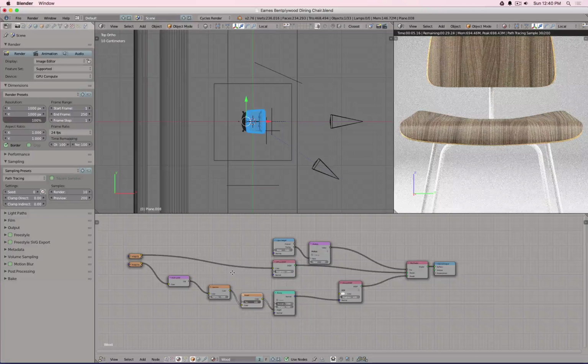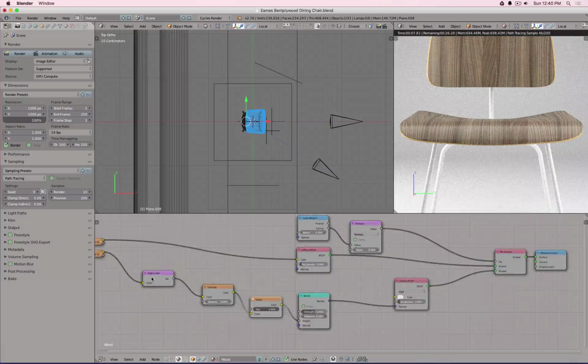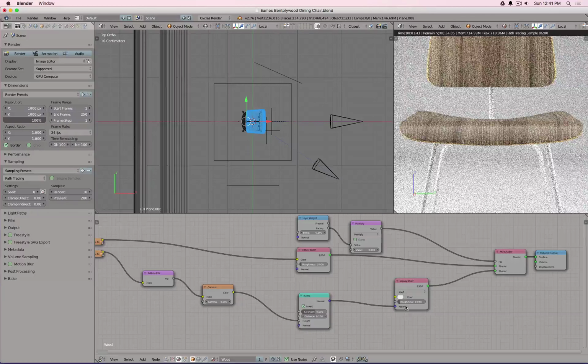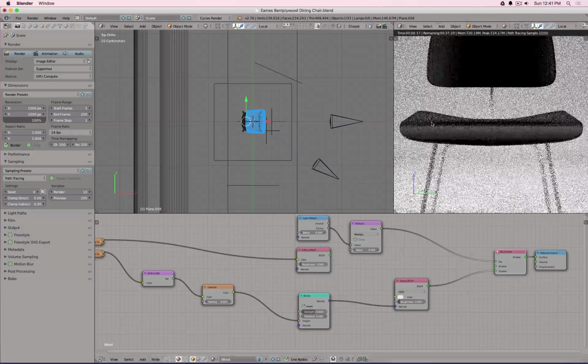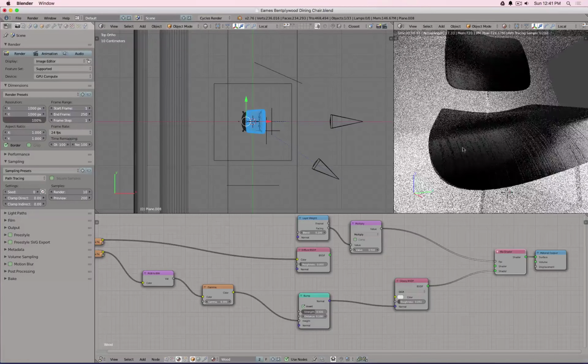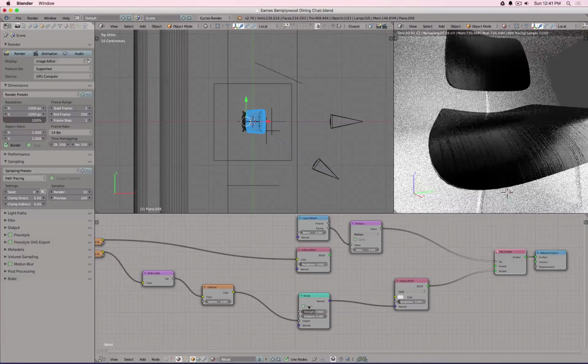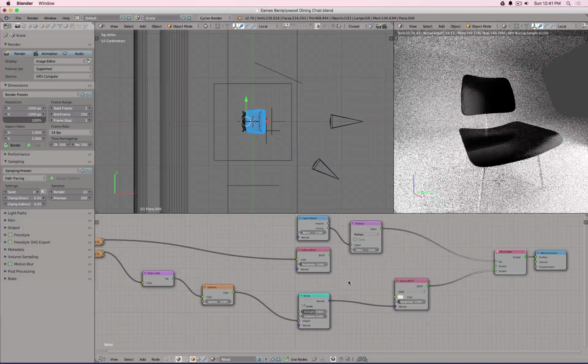So we can maybe leave it at this. Grayscale, and then with the gamma node we adjust the black and white and clip it, and with the invert we flip the image so we have the correct bump direction. Actually, I'm a nerd. There's an invert button built in. Sorry, overlooked it. Old habits sometimes die hard. So there, we can do it directly this way. Perfect.